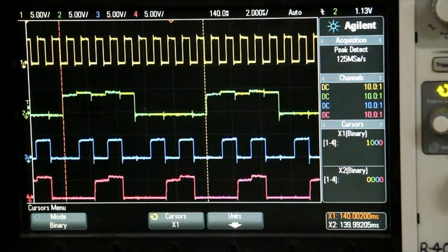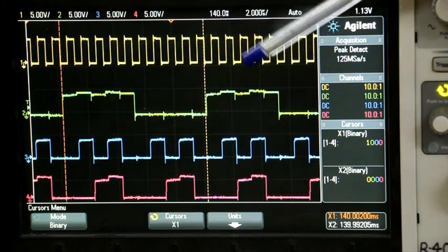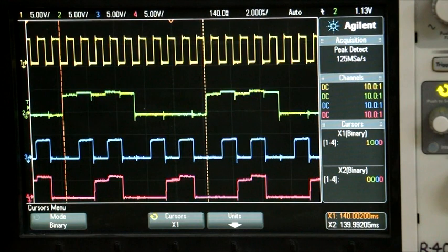So therefore you would get an exactly divide by 10 with a high and a low which are symmetric. And for some applications this may be important. If you are only interested in the frequency, then using the QD output in a BCD mode may not be the right thing to do. Instead you could use this Bi-Quinary mode. So that's the advantage of this particular mode.